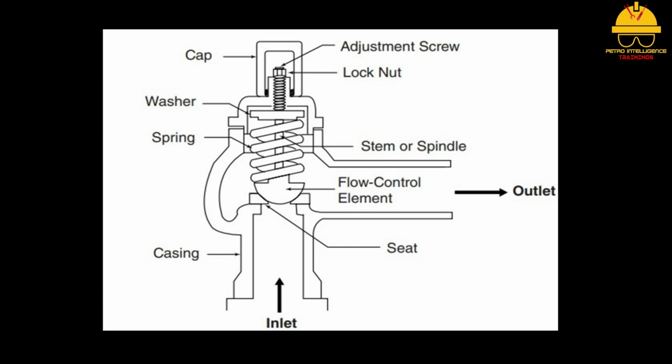Steam cut and wire drawn are two terms applied to damaged trim. Relief valves vary in design and style. Relief valves have a specific amount of travel, or lift, which varies from fractions of an inch to several inches. When a relief valve is lifted until it completely compresses the spring, it is said to be in the fully open position. The difference between the initial liftoff pressure and the pressure of the fully open position is called accumulation.